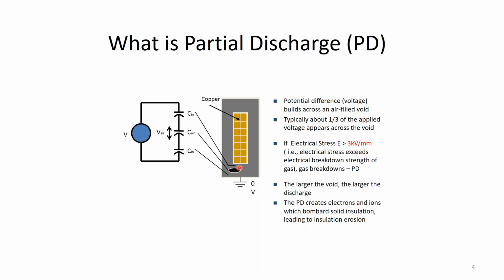What electrical breakdown is, is where you essentially rip the outer electron in an atom or a molecule, especially a gas molecule. Because of the electrostatic forces, you're able to rip the electrons away from the atoms. And if this is, for example, positive at this part of the AC cycle, those electrons, which are negative, will flow across that void. And because we have charge moving through space and time, it will create a current, I equals dq by dt, if you've got an electrical background. And so every time there's a discharge, it creates a current pulse. And this is what we're measuring.